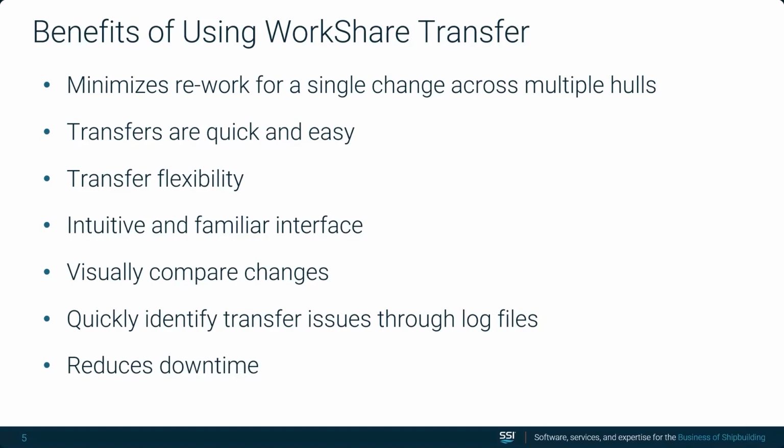And a last key advantage that I'll highlight regarding WorkShare Transfer is its ability to significantly reduce downtime. Unlike other WorkShare tools, which often require users to pause their work during transfers, WorkShare Transfer allows users to continue working within the project. The only restriction is avoiding work in model drawings within the destination project that will be affected by the transfer. Essentially, the rest of your project remains fully accessible.